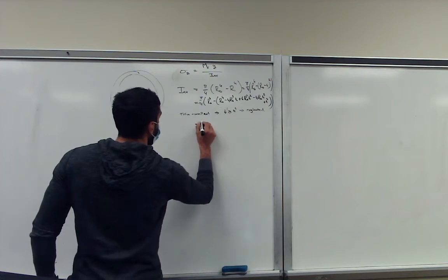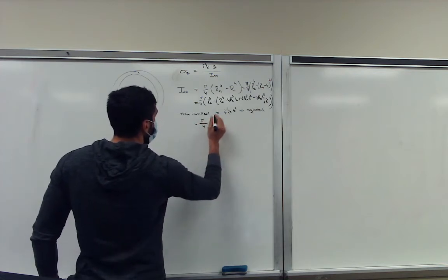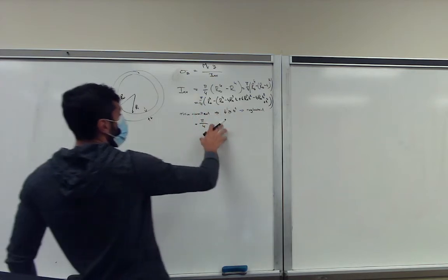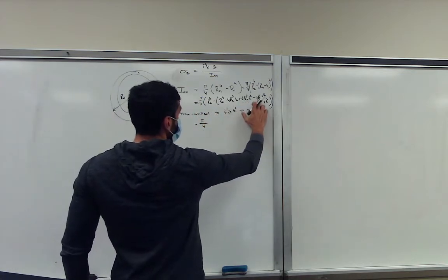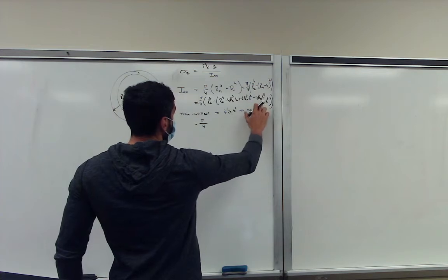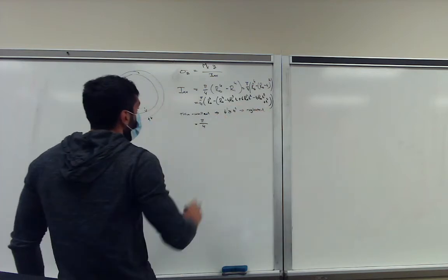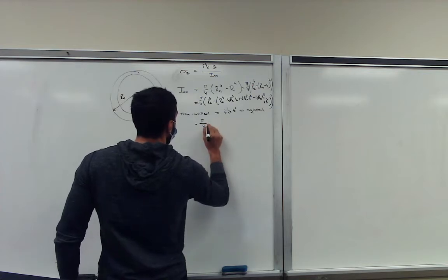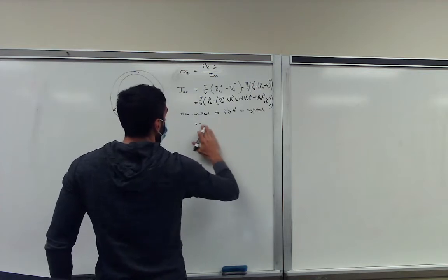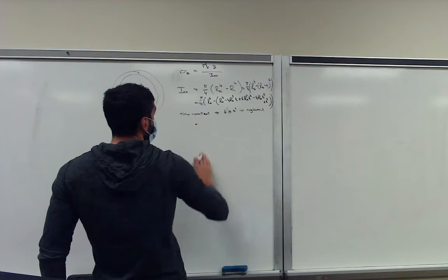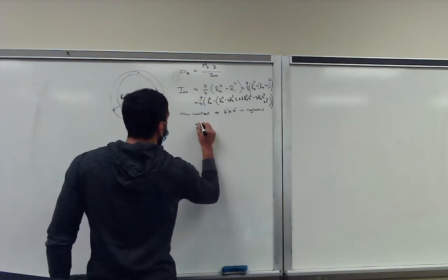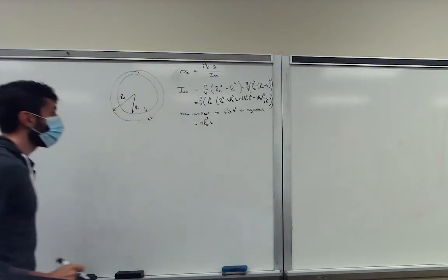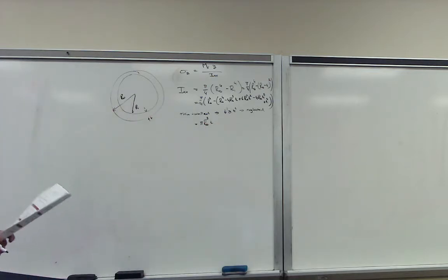So what we get is, in this case, these r_o^4 terms drop out, cancel each other out. This is t squared, t to the power 8, t to the power 4. So those all drop out. We get only minus becomes plus. So we get pi over 4 multiplied by 4 times the outer radius cubed multiplied by t. So we get pi times the outer radius cubed multiplied by t. So that's our moment of inertia.